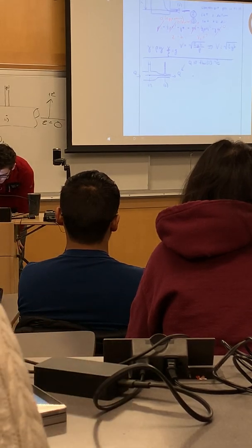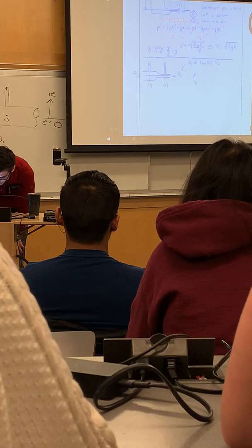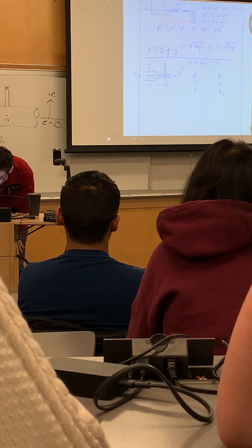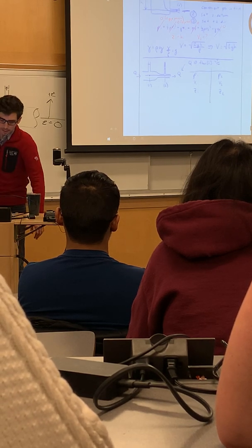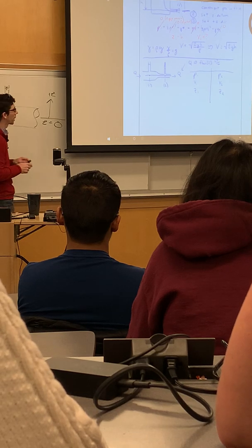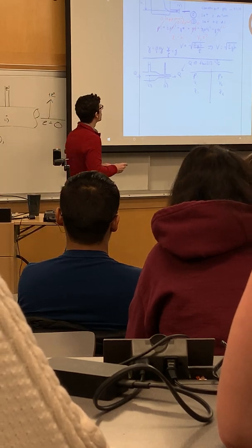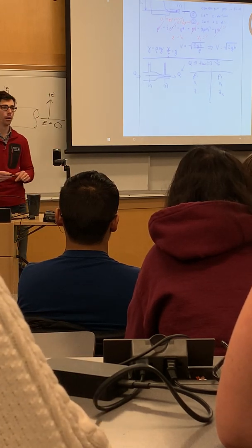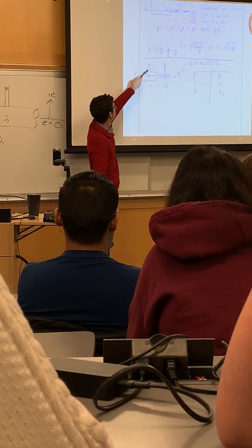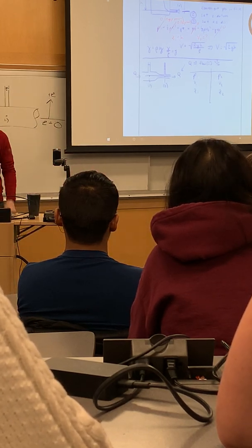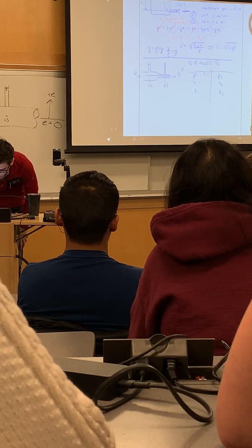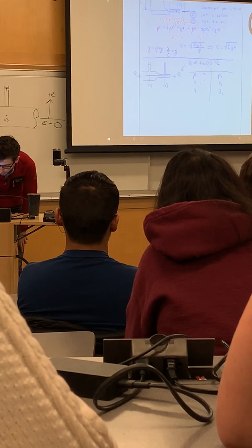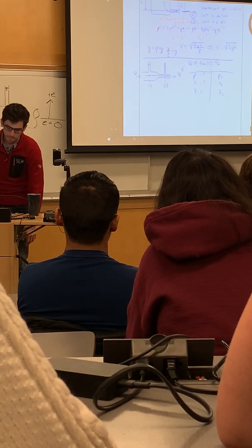So in this case, what do we have happening at point 1? Let's just denote the important terms. We have P1, V1, Z1, and P2, V2, Z2. So let's just review whether we think these are things we can ignore or cancel out or not. So at P1, is there static pressure at P1? Yes, right? I mean, the piezometer is telling us that there is. So this is equal to some number. We have velocity at point 1. Yes, it's a flowing fluid, there's velocity. What about Z1?